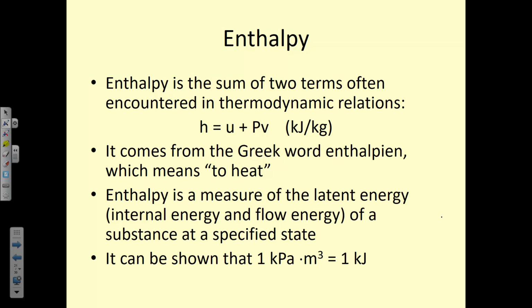Okay, enthalpy is the sum of two terms that we often encounter in thermodynamics. That's internal energy plus this pressure times specific volume term. So it's another energy term, and it represents the internal energy of the system plus the energy of flow or expansion. So when we're talking about enthalpy in terms of an open system, we're taking into account not only the internal energy of the fluid, but also the energy that's required for that fluid to move through the system. So it's a combination term.